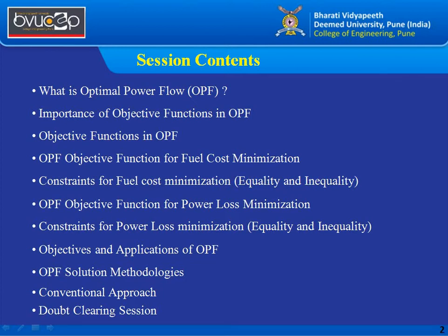So this optimal power flow analysis is going to be the solution for those real time variables, because it helps to get the real time data, even in complex form, and it takes very less computation time as compared to the normal load flow, because here we consider the control variables with some constraints so that the system remains intact with the grid. That is, the system should be secure. The security of the system is the priority for us, so we have to maintain it.